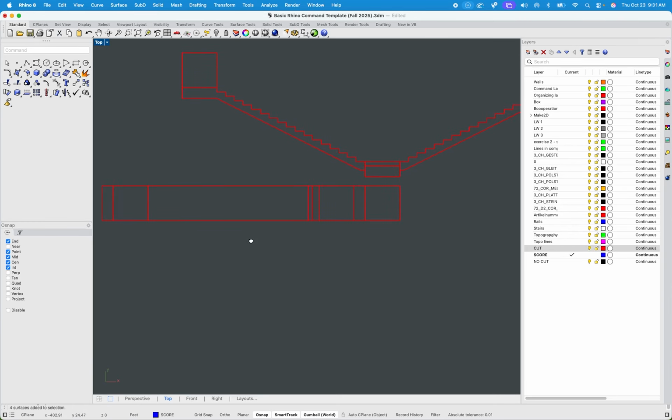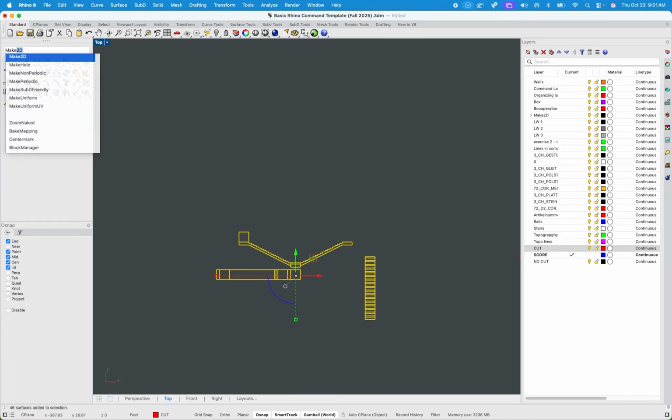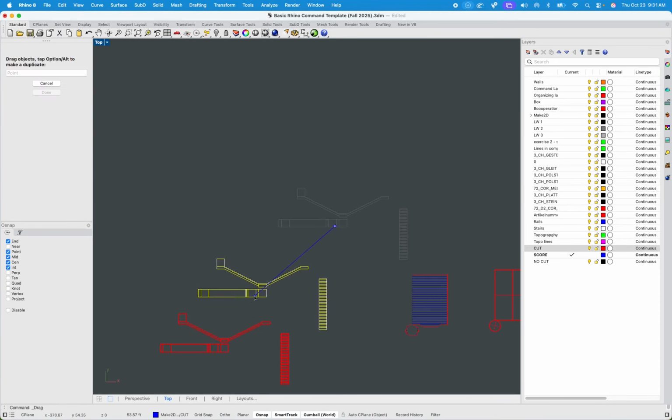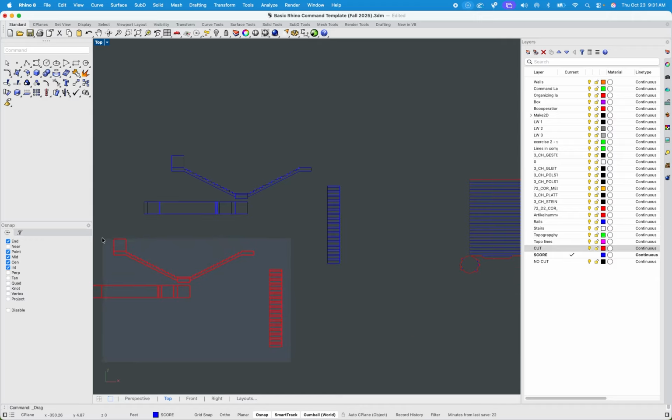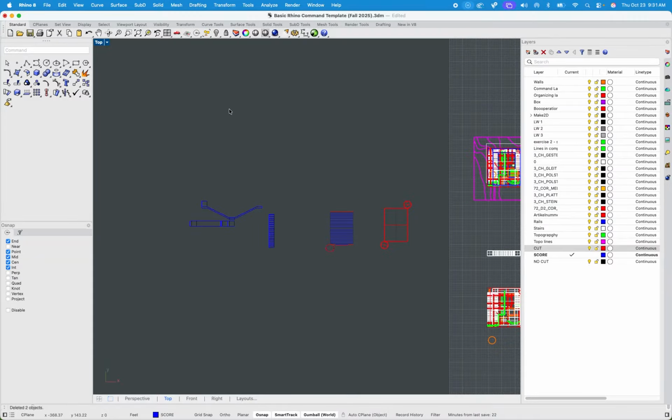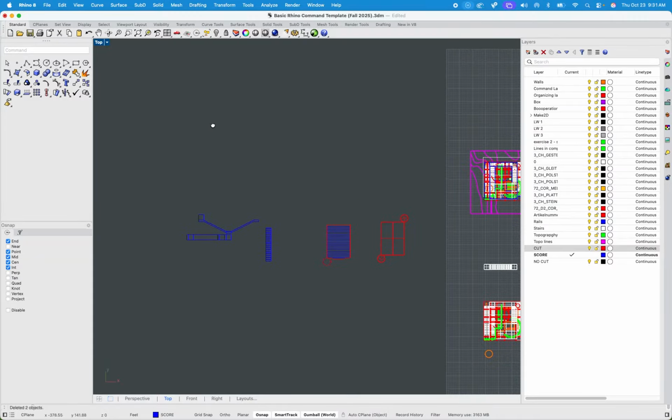Ah, so what do I have to do to that? Make 2D, right? Keep in mind, it is actually still a three-dimensional polysurface. You can't just 3D print or laser cut polysurfaces. You can only cut lines. So we do still have to make 2D. My bad, I misspoke earlier. There's the one that we can actually change. This one, get out of here. We've already unrolled you. You're fine. But as you can see, I have to do this piece by piece, and I really do have to methodically think about each piece and how it's going to be cut by hand or by laser cutter.